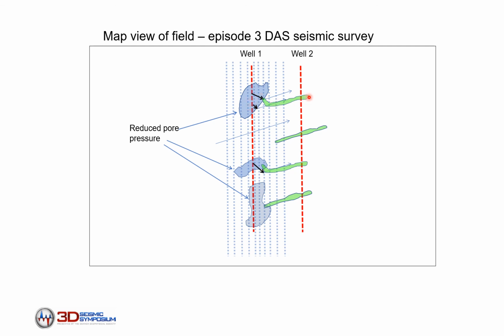Also, if we're pouring frac energy and dollars into this side toward the low pressure zone, we aren't going to get the penetration into this side of the reservoir that we want, as opposed to maybe a zone like this where we don't have pressure drawdown nearby, and we might get more of this bi-wing frac that we're really interested in.